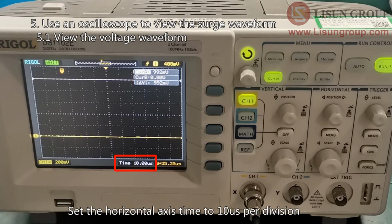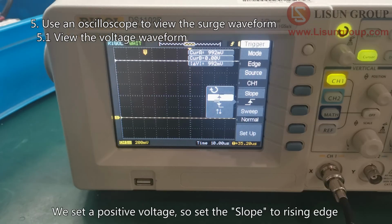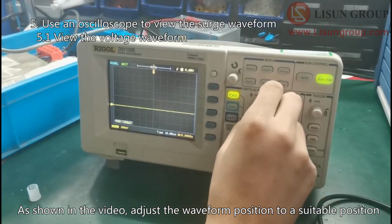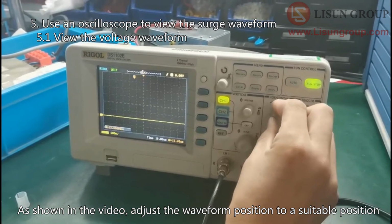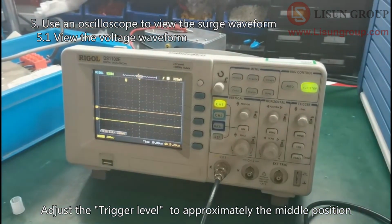Set the horizontal axis time to 10 microseconds per division. Set the probe multiple to 1. We set a positive voltage, so set the slope to rising edge. Set the sweep to normal. As shown in the video, adjust the waveform position to a suitable position. Adjust the trigger level to approximately the middle position.